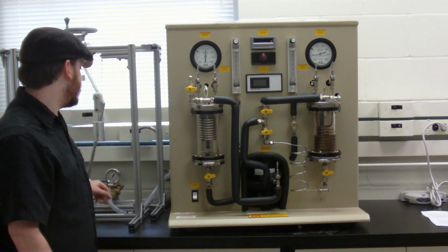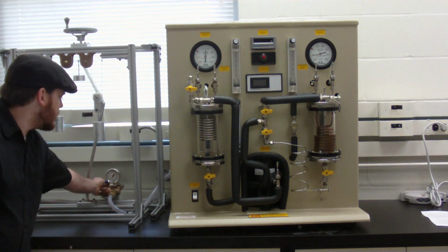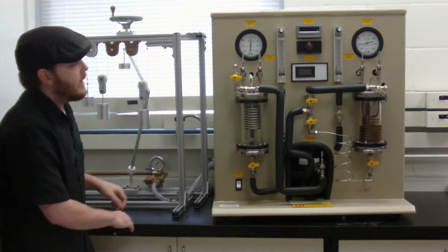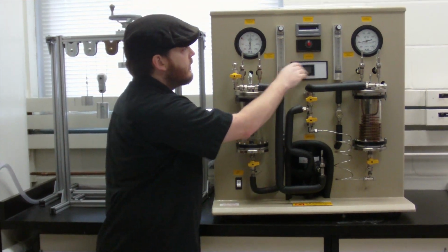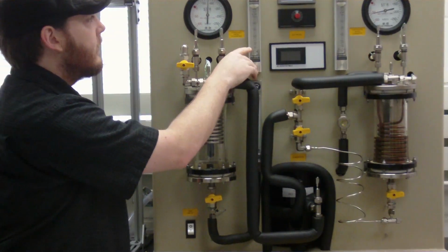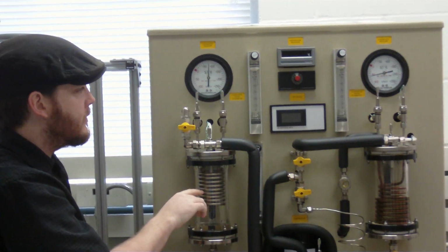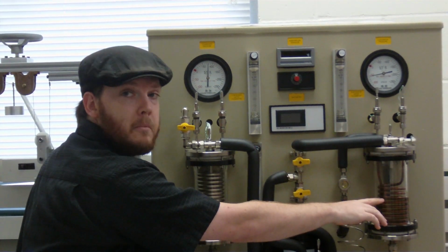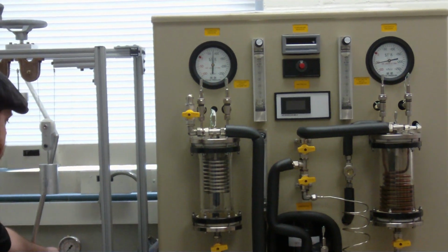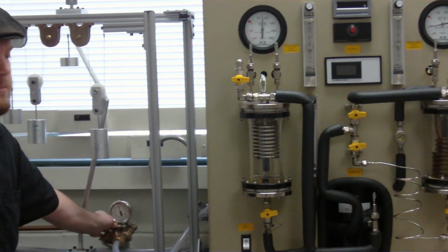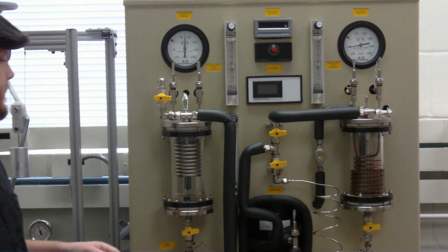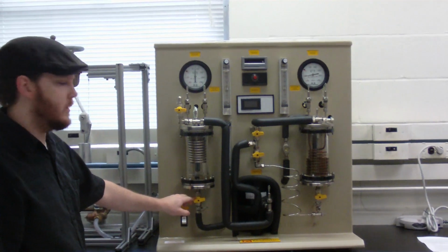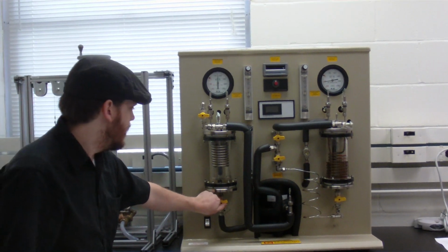The first thing you want to do, if the water is not already running, is turn on the water valve. You'll be able to hear it. You may not see a flow. However, you can check these two flow meters, as this is the flow meter of the water running through these condenser coils, and the flow meter for the water running through the evaporator coils. You turn this on, you'll hear the water flowing, and you can now turn on the valves here to open up the line for the refrigerant.